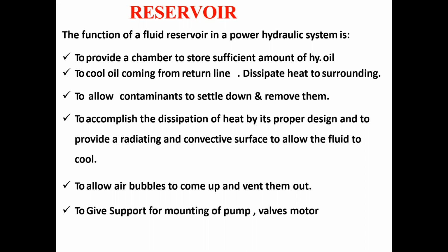Then, to allow contaminants to settle down and remove them. When oil moves through the various pipelines or through the system, it may come back along with some contamination or foreign material. So when this oil returns along with these contaminants, it is desired that the reservoir allow them to settle down. Settle down means to sit at the downside, at the base of the reservoir, so it can be removed easily from the reservoir.